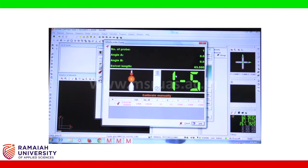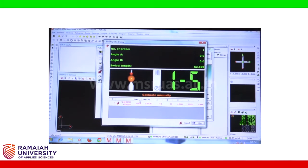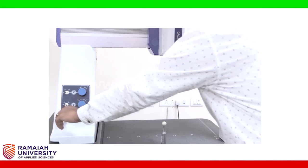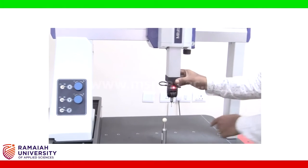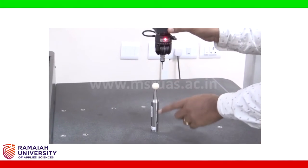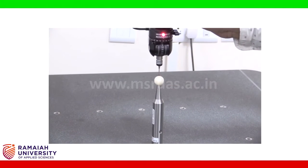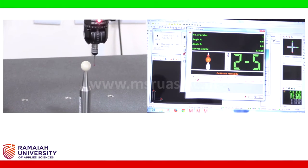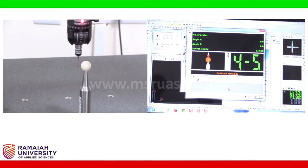Now the CMM is asking for the first point out of the 5 contact points, and you can see all the probe details. Probe number 1, angle A0, angle B0, sleeve length 63.500. Now let us start measuring the probe. Now I am going to get the first point. This is the crystal ball. This is the master probe. I got the first point. Second point. Third point. Fourth point.